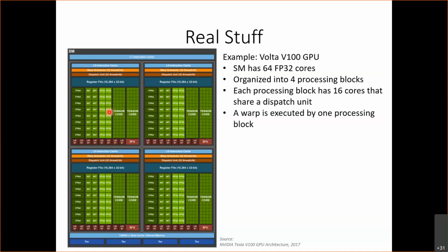But what if we get different warps, for example, floating point 32, floating point 32, then we get integer. If all the floating point 32 execution units are busy, we will be doing nothing while we could do the integer operations. I see what you mean. You're talking about interleaving instructions from different warps. I will talk about that. But within a warp, the instructions are going to execute in an in-order manner. These are in-order pipelines, not out-of-order pipelines.